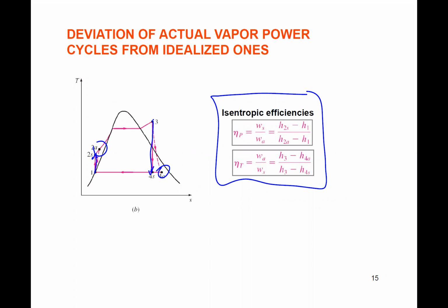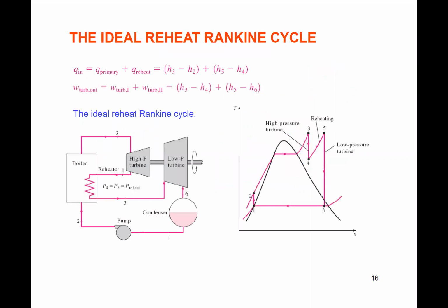So this is vapor, so this is where we have to use our tables in this chapter, right? So this is our A4 to A7, okay, for water. Reheat, so adding some components for a little bit more efficiency or more work. Okay, so reheat, we just have this additional heat addition: we expand through one turbine, add that heat, and then expand again.